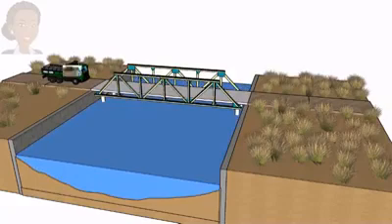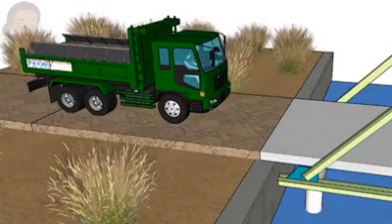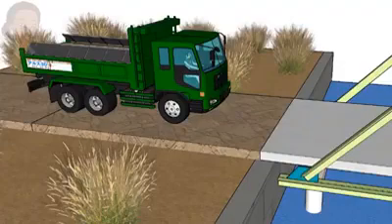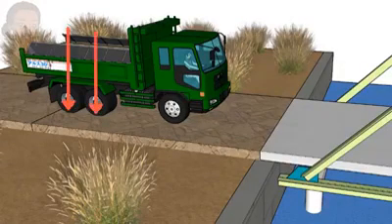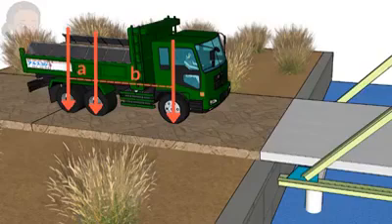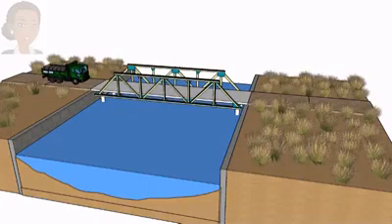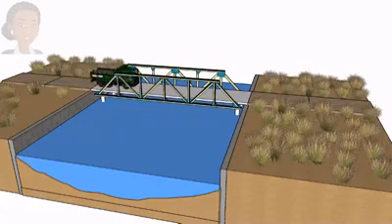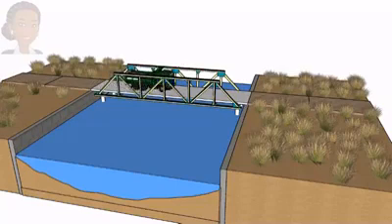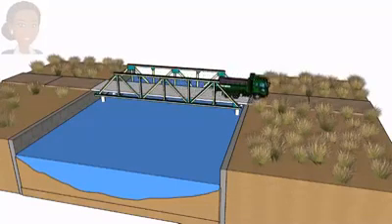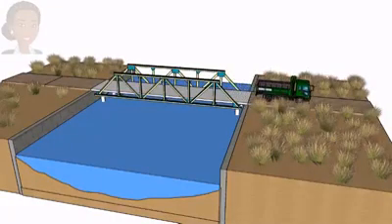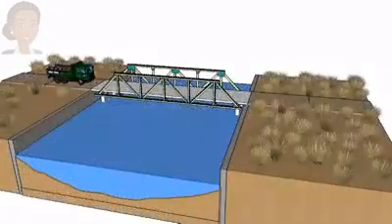The bridge is expected to support the maximum load of a truck having 3 axles. For the sake of our analysis, this can be viewed as a series of concentrated loads spaced according to the distance between the axles. So, we wish to determine the maximum impact that the moving load series could have on a given truss member. More specifically, we want to determine the truck location on the bridge that induces maximum axial compressive or tensile force in the member. We can solve this problem using influence lines.